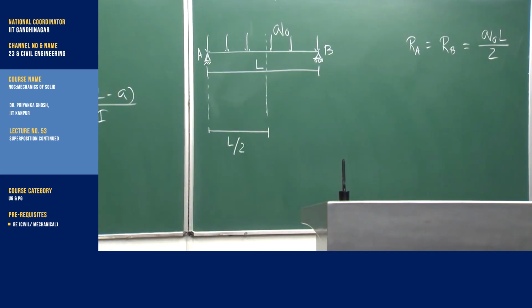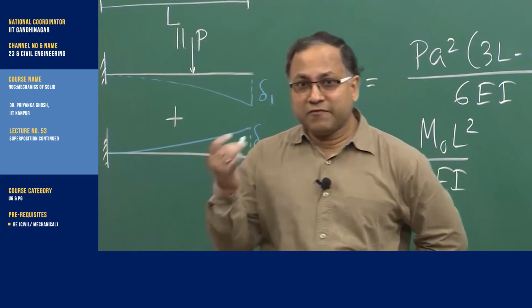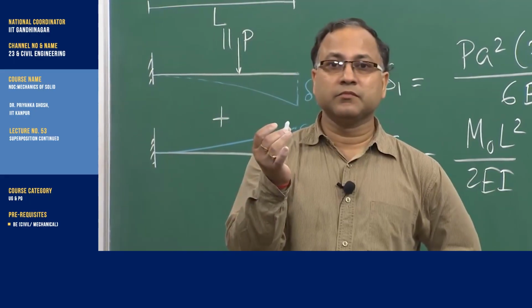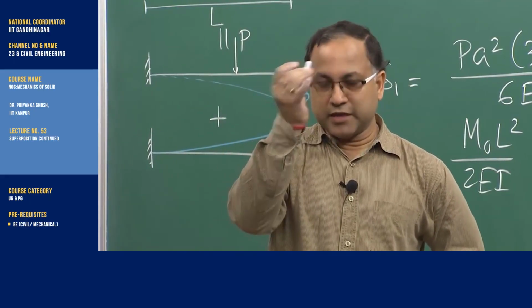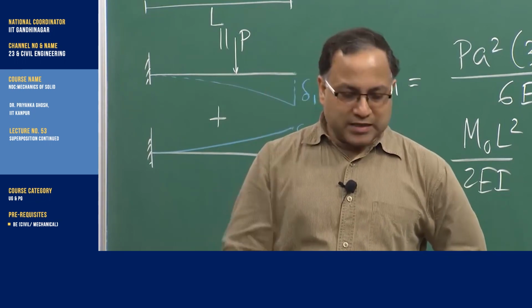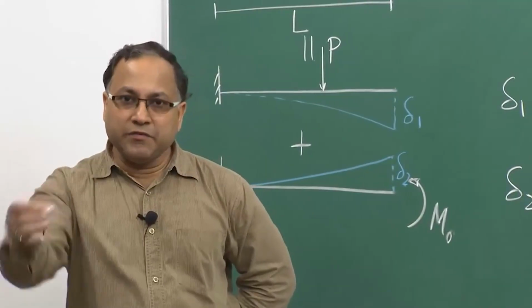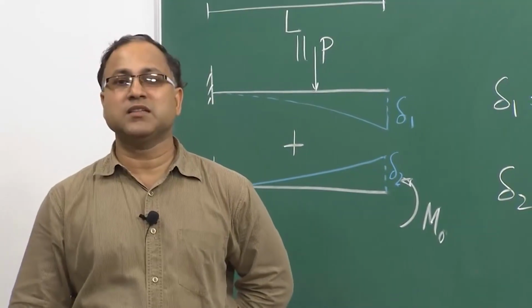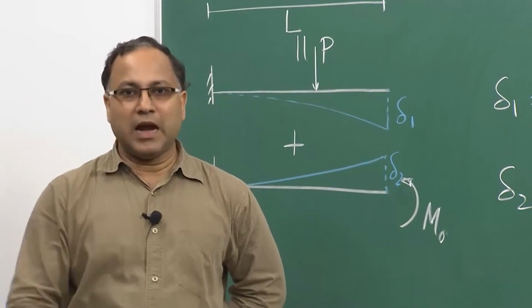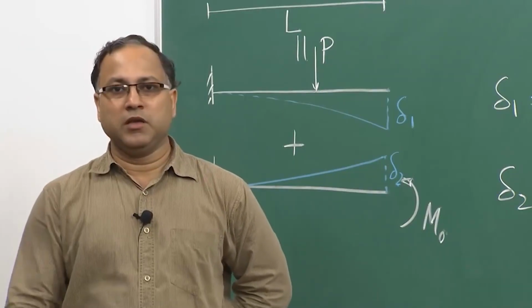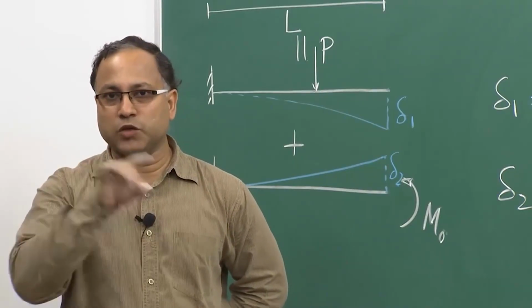Now, at the mid span of the beam, under this kind of symmetric loading, it is quite expected that you will be getting the maximum deflection, agreed. If you get maximum deflection, then your dV/dx must be 0.